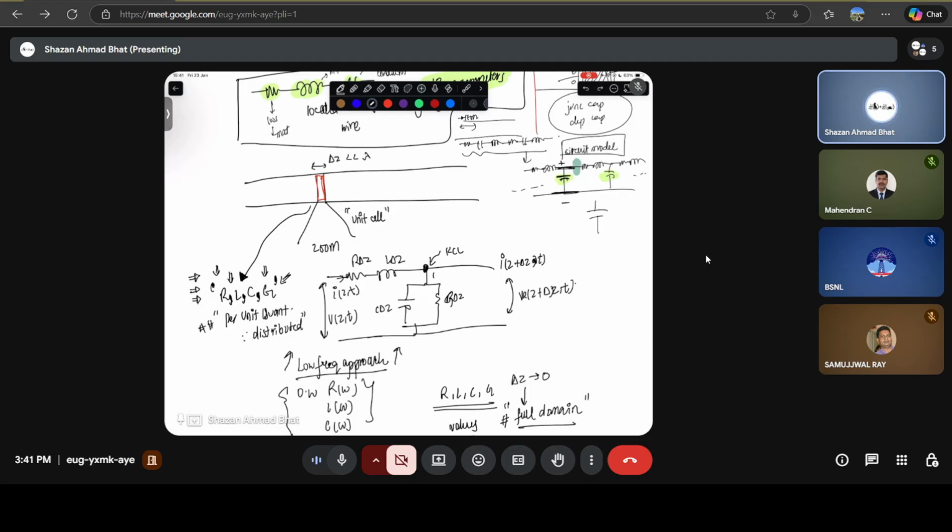That's why you don't have inductance here, because there is no current flow in this direction. Current is only flowing here or here. There is no current flow here. There can be something called leakage currents, but that is not of our concern. We'll talk about it later, because the leakage current can flow through a capacitor, but that's basically a short, which is not desired. But that's why the inductor doesn't appear here in this direction.